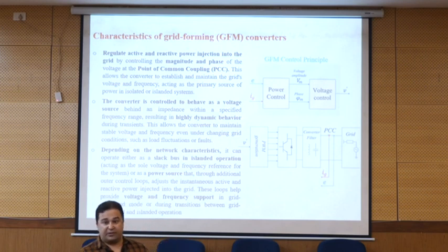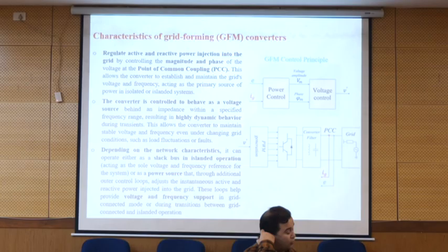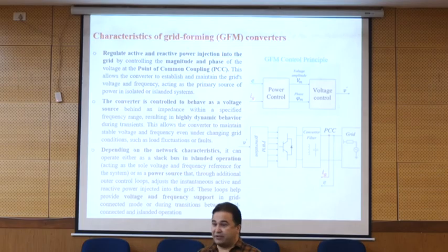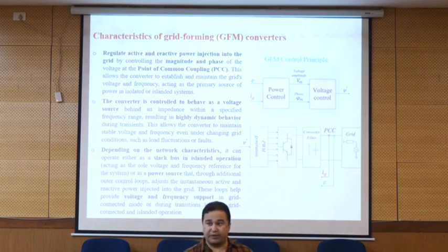Okay, but in power quality, as I talked about yesterday, when we are talking about power quality, in fact, we are talking about voltage quality. So at the end of the day, if you are going to provide electricity to the grid, both the THD of the current and voltage should be less than 5%. But on the load side, we are responsible as a DSO to provide voltage less than 5%, but the current depends on the customer side. Okay?